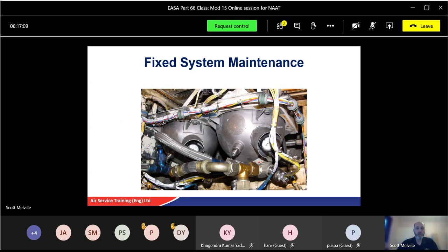Pin type indicators should be checked. They're flush with the cap, so you put your hand up there and make sure the pin is extending out, which would say it's been discharged. And again, you're just checking for normal damage. If you're fitting the ones with the cartridge units to extinguishers, again, check for corrosion and damage. The date of manufacture should be stamped on it, so again, it will tell you the life.